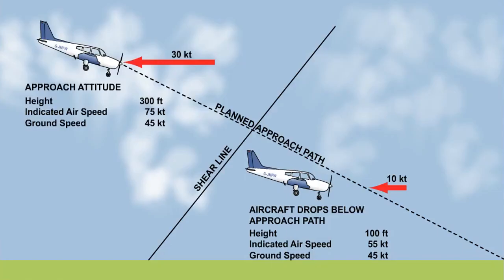The greatest potential risk posed by wind shear to aircraft of any size or type happens at low level and low speed, where an aircraft is vulnerable during initial climb and approach to land. In particular, on the approach, the aircraft is at low level, low speed and low power, and because of that it has a relatively low total energy to overcome potential problems.